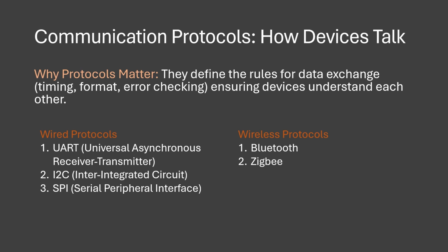So now, how do you choose a protocol to use? For example, if you have some sensors that can communicate over different protocols, which one are you going to use? The first thing you have to consider is speed: how much data needs to be transferred? You also have to consider the number of devices that are available. Another thing to consider is reliability, how reliable it is. Should you go for a Bluetooth connection or a wired connection? Also, you look at the power consumption.